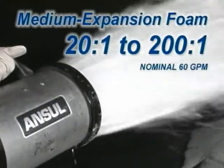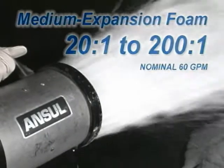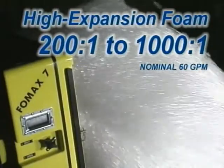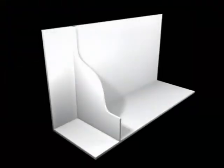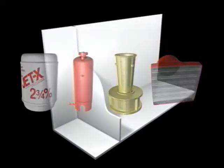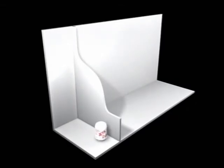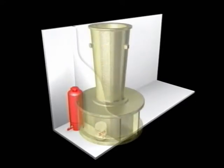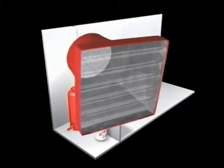Medium expansion foams range from 20-to-1 to 200-to-1, while the ratios for high expansion foams range from 200-to-1 to approximately 1,000-to-1. The typical high expansion foam system consists of four major components: JetX high expansion foam agent, a bladder tank sized to fit the application, a foam proportioner, and one or more high expansion generators.